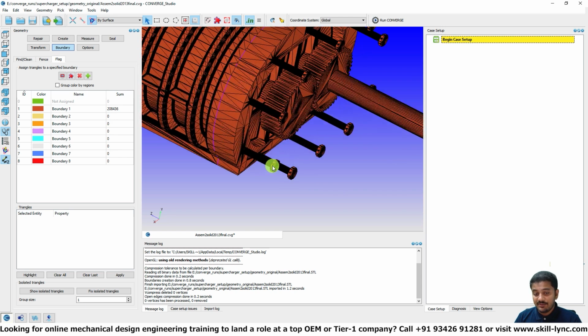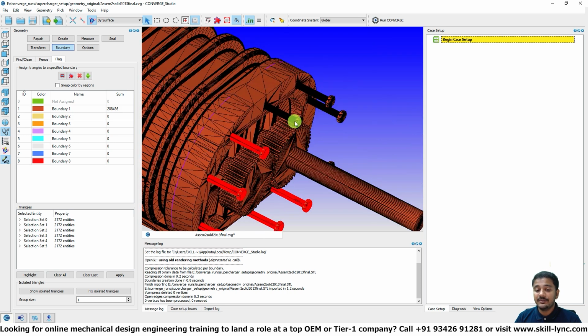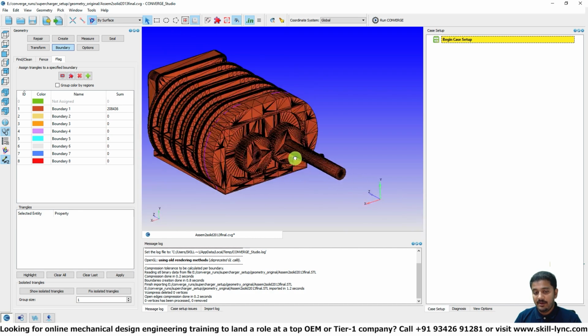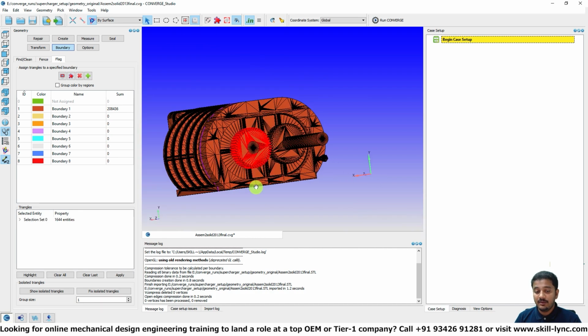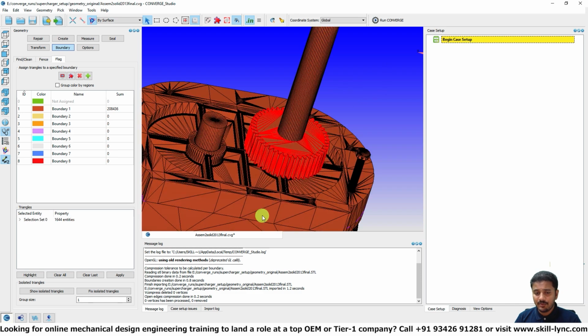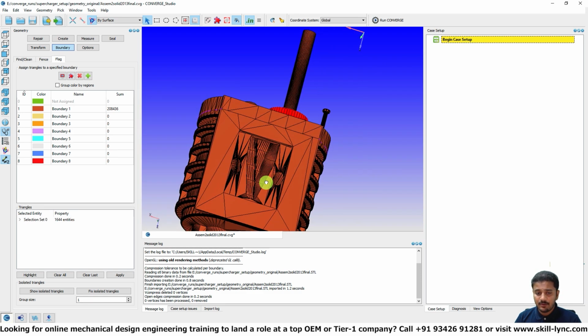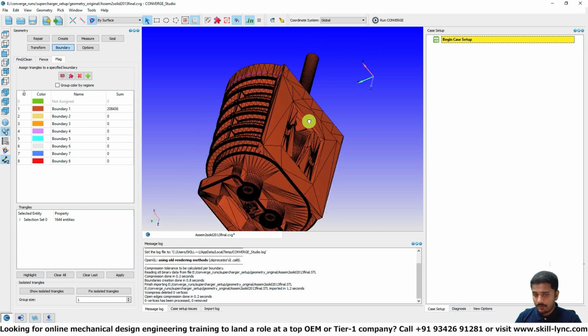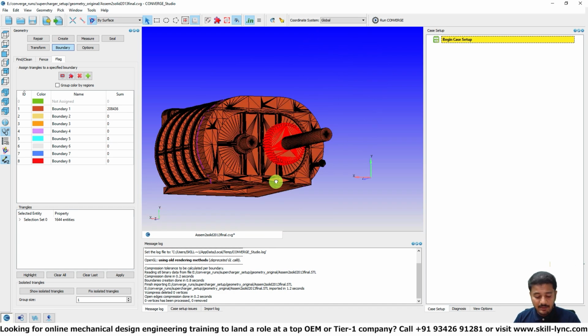So how about these guys, the bolts? Yes, there you go, you can select them. So this is the nice thing about the surface option. It helps you select quantities in bulk and quantities that are not connected. So let's just delete it. Alright, so how about this gear? Cool. So it looks like this gear is also separate, so let me delete that, which means this one should also be separate. Now I need to be very careful. I need to make sure that no other components are selected when I do this. So I'm going to go ahead and delete this guy.